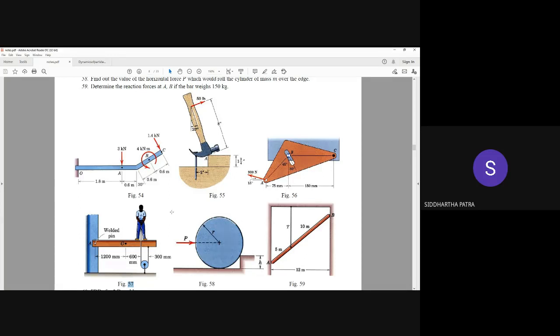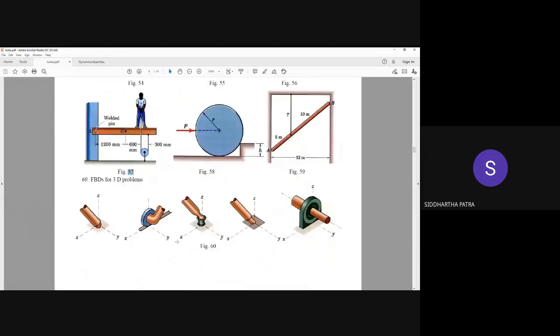If you draw the free body diagram of the person, and then calculate how much normal force he is receiving from the beam in order to be in equilibrium, and then put that normal force in the reverse direction at that location, that is justified. If not done in that way, you cannot simply write whatever force must apply at that location.